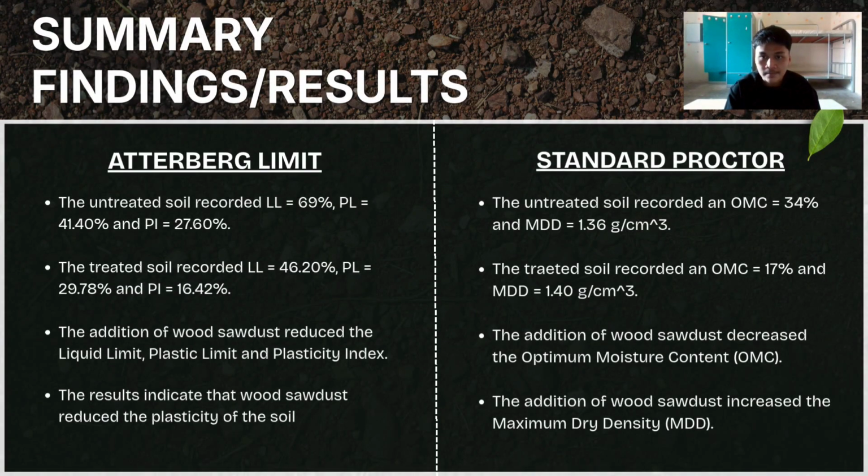Summary of findings. For the Atterberg limit test, the untreated soil recorded a liquid limit of 69%, a plastic limit of 41.40%, and a plasticity index of 27.60%.